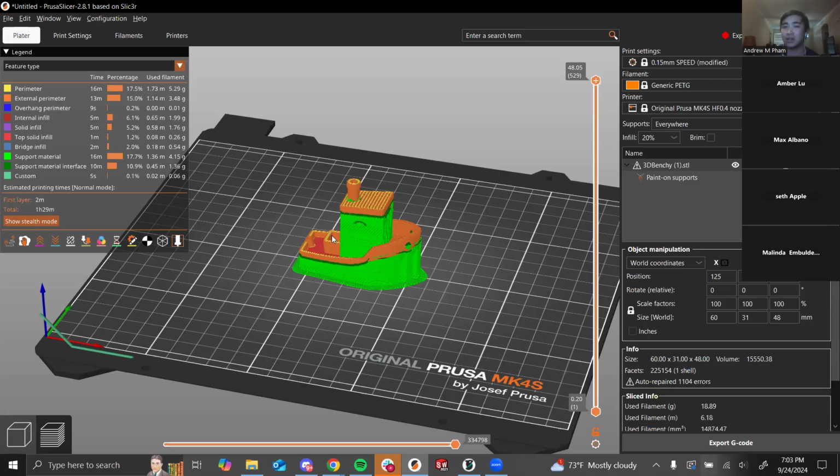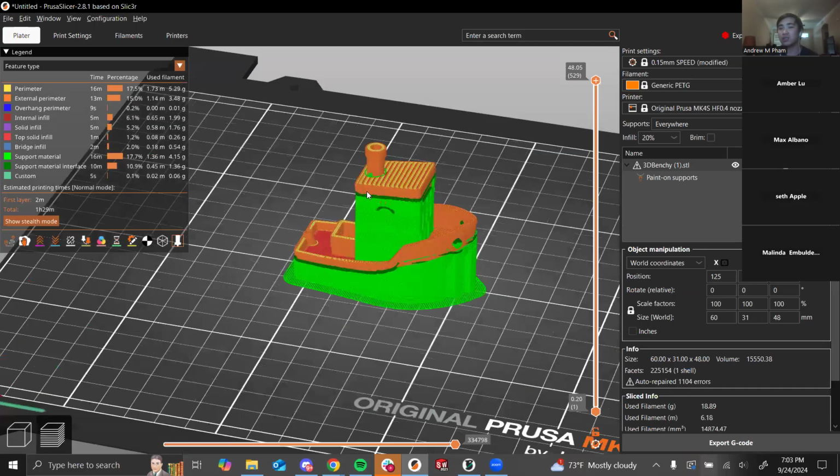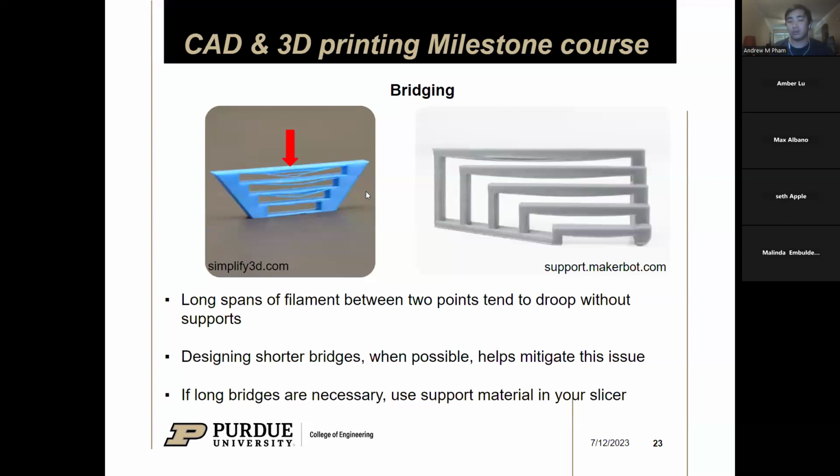Generally for stuff like walls, I like to keep it at a 2 millimeter minimum, and that's the absolute minimum. I try to keep things at least above 3, because anything smaller than that might have a tendency to break depending on the geometry. So again, when you go to design your finals, please don't make super thin parts, because there's a higher risk of your part breaking once you receive it, or even breaking as I'm taking it off the print bed. So yeah, please don't make really small things.